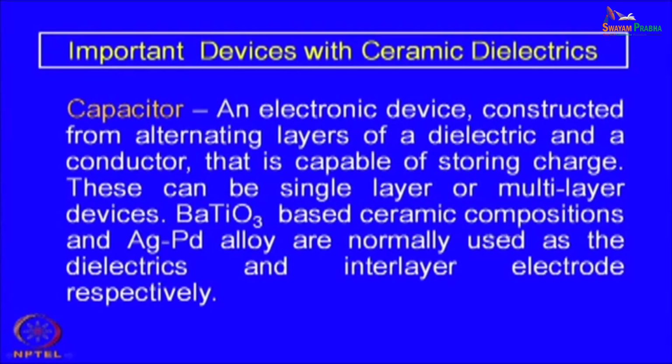Barium titanate based ceramic compositions and silver palladium alloy are normally used as the dielectrics and the interlayer electrode respectively. This is for the multi-layer capacitors. Of course, the capacitors which so far we have discussed are basically single layer, that means a single layer of insulator and two layers of metal electrodes.